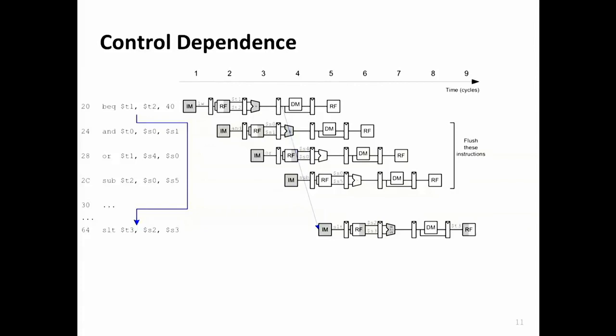So you do that computation over here, and then latch the target address, latch the condition, and based on that condition, you need to redirect the fetch engine. But you've already fetched 3 instructions over here. If the calculation says that you should jump to the target, you need to flush these 3 instructions and redirect the fetch stage to the correct program counter over here. That's what this is showing. So you basically wasted 3 instructions, right?